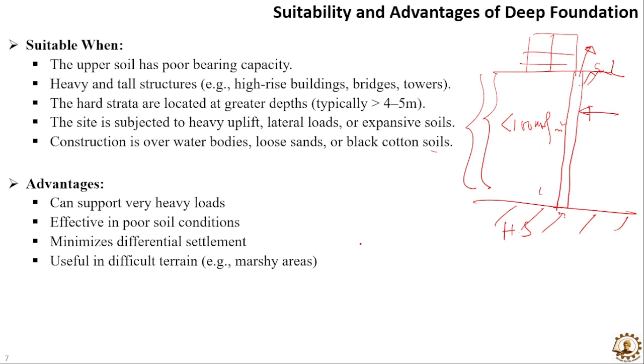The advantages of deep foundation are that it can support very heavy loads, much heavier than a shallow foundation can take. It is effective in poor soil conditions, where the soil has very low bearing capacity. It minimizes differential settlement, because as we rest all the piles on the hard stratum, the total cumulative settlement will be the same for all the piles.